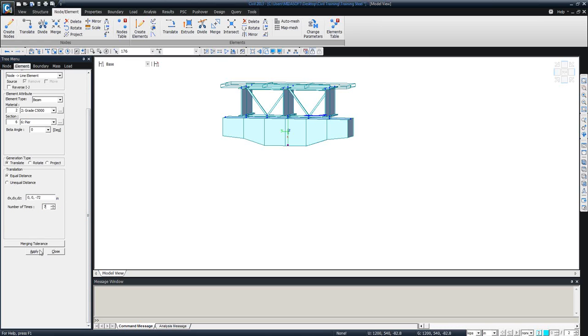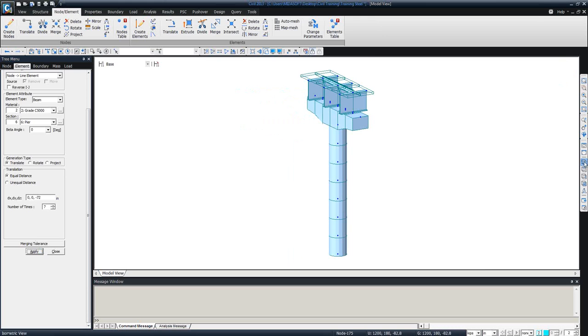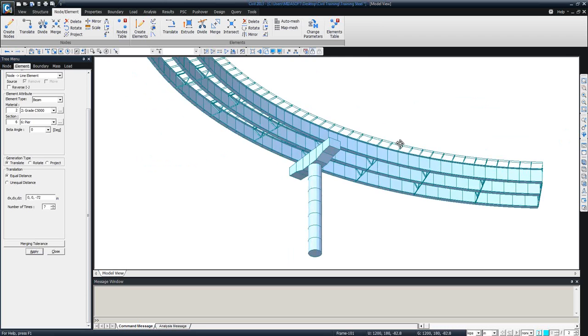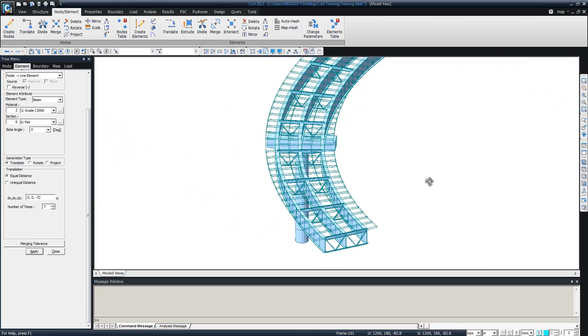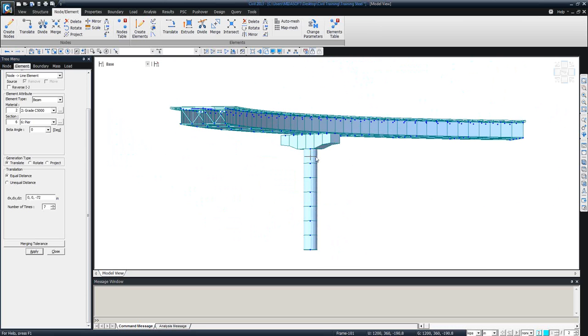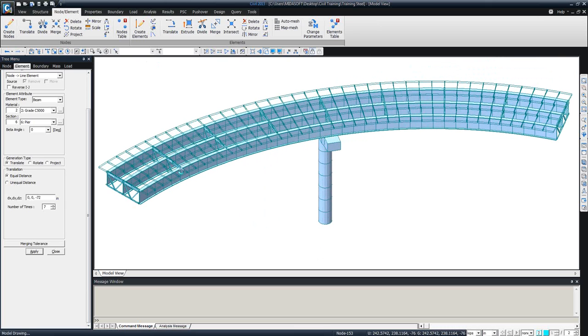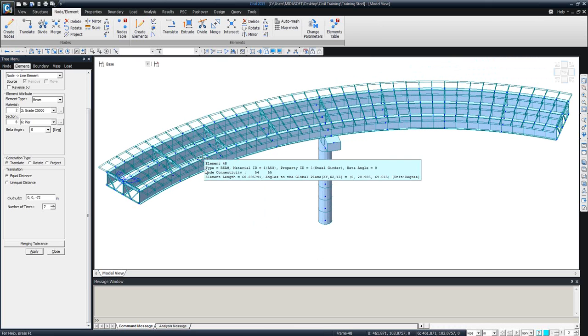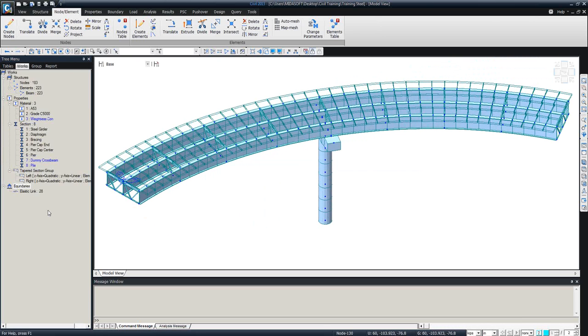And just ensure that it's negative, and going downward is already created. And I can just activate the entire girder. So far I have the girders and the cross frames, and then the pier cap, and then the pier. All right, we just ensure that you save your model time by time in case you may lose your data. Close. And the next part will be modeling the abutments and also modeling those cross frames.